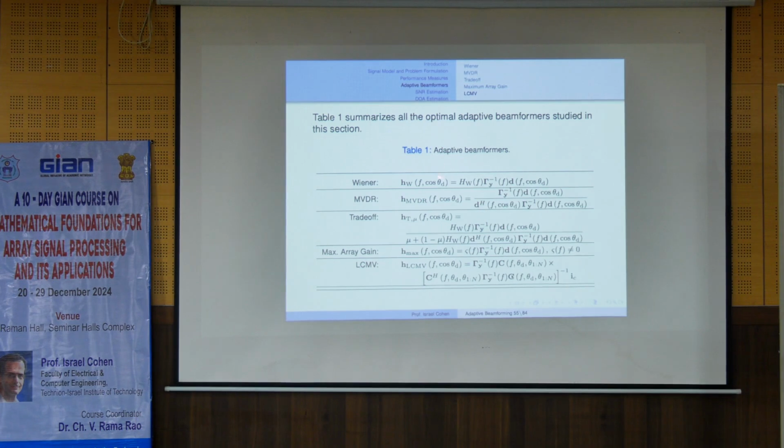Okay, so you see, adaptive beamformers, we need to estimate the direction of the desired source. We need to estimate the correlation matrix regarding the noise. We need to estimate the environment. Because of this estimate, and we have a limited amount of information, sometimes the correlation matrix is inaccurate.